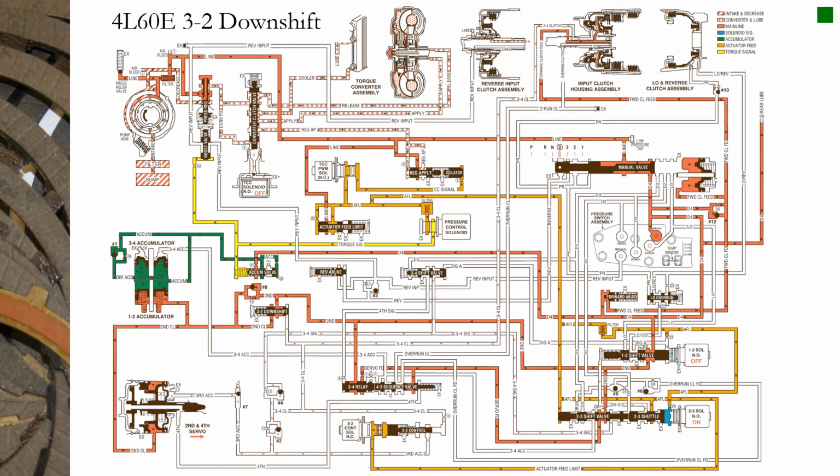So I don't know which one necessarily was the one they had to work out the most, but they have to operate this 3-2 control solenoid. By operating the 3-2 control solenoid, they either force the fluid, when it releases, to go through both of these orifices, or it can bypass orifice number 12 and just get forced through orifice 13. So really the whole purpose of this solenoid and this valve is to determine whether fluid has to flow through 12 or it can go around it.